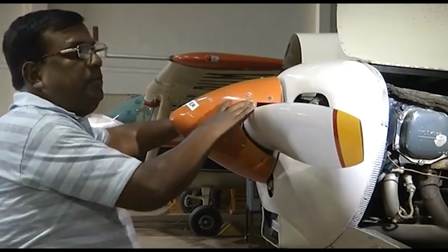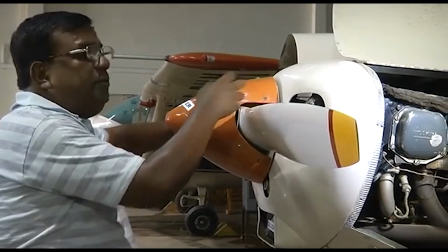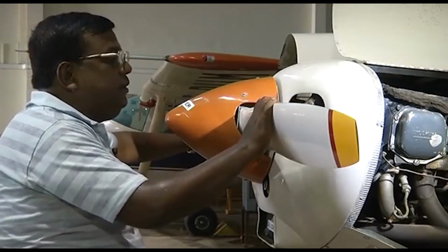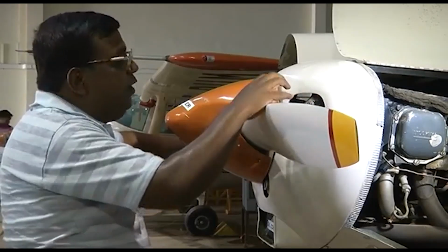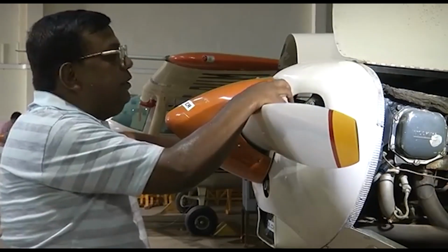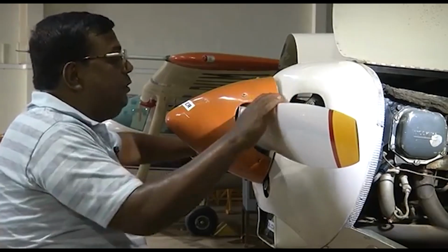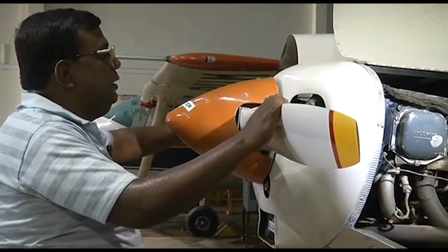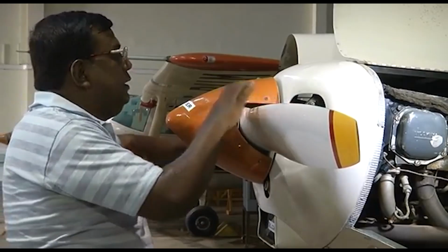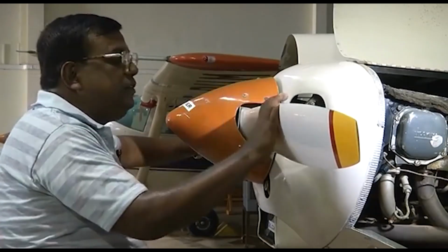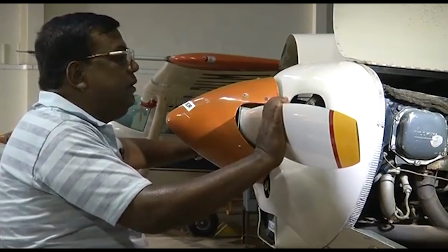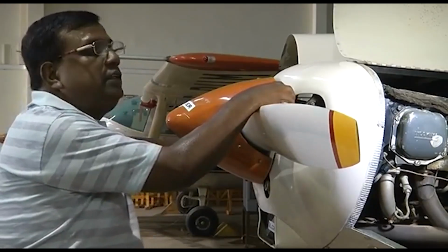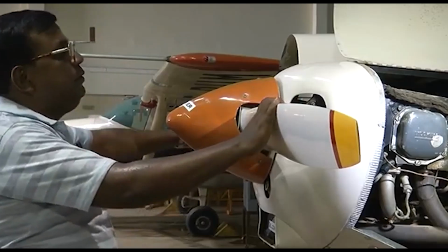Whatever energy is burnt in the fuel in the cylinder delivers power at the crankshaft, and when I attach a propeller, the propeller draws that power, but the propeller has its own efficiency. It will have some losses, so you will find that whatever power is available at the crankshaft, or the brake horsepower as we call it, the power being used by the airplane is less. That is, there is a propeller efficiency. This efficiency could be 90%, 95%. So 95% of the power available at the brake or the shaft is utilized by the propeller to drive this airplane.